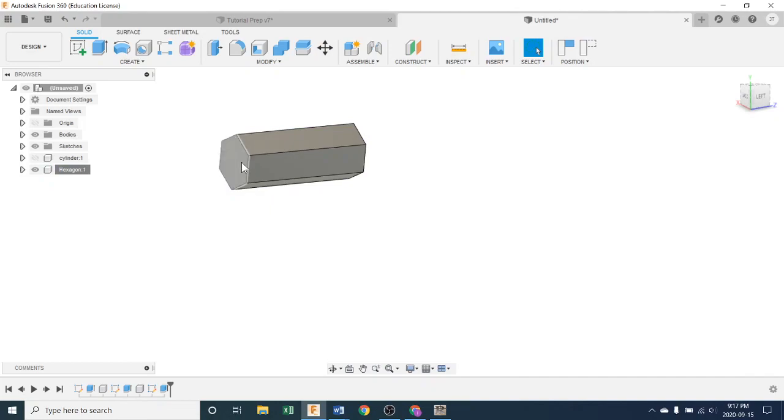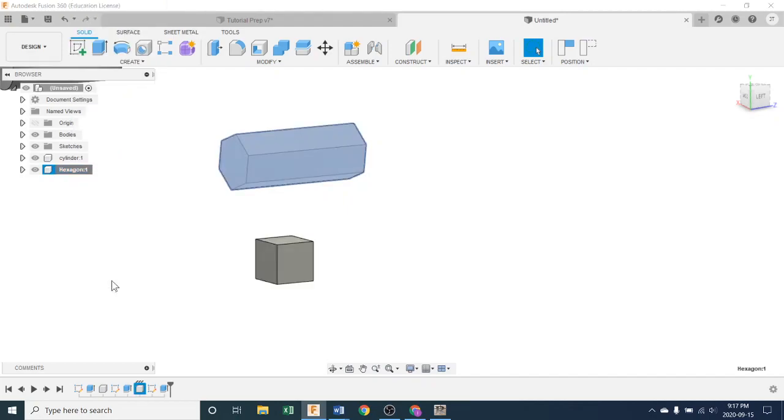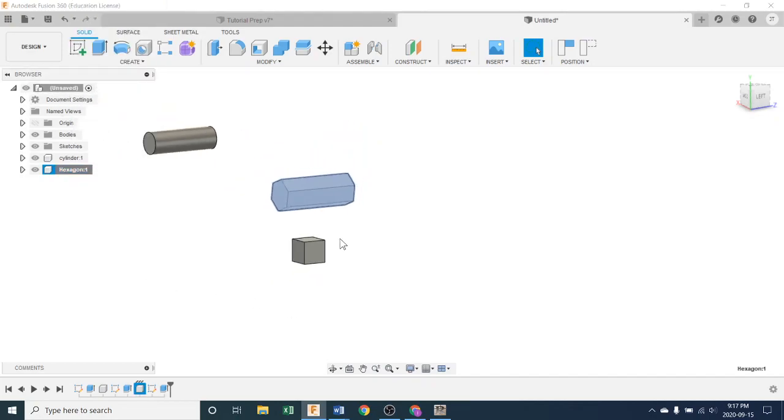This is super important. When we draw our first robotics robot, it's very complex. It has many, many parts. And I want to just work on one part, and I want everything else to go away. So all I do is find that part, right-click, isolate it. Everything else is gone. I draw on that part, whatever I have to do, and then I go back, right-click again, and I unisolate it. It's just a toggle.